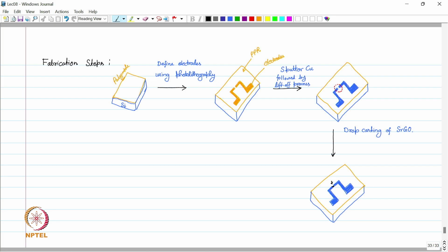So we can now remove the back silicon wafer, which acts just like a handle wafer, just for our convenience or to give mechanical strength to the polyimide. So now we can remove this silicon wafer from below this polyimide sheet, and this polyimide sheet will come out. Now with removal of the polyimide tape from the silicon substrate, and then finally we have a polyimide sheet only with this electrical structure. We have this polyimide sheet.